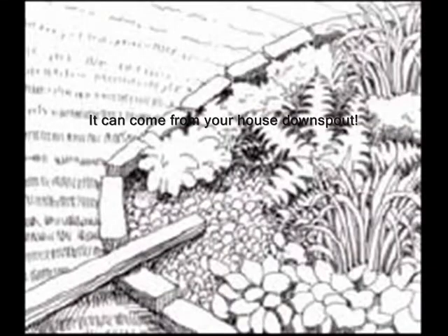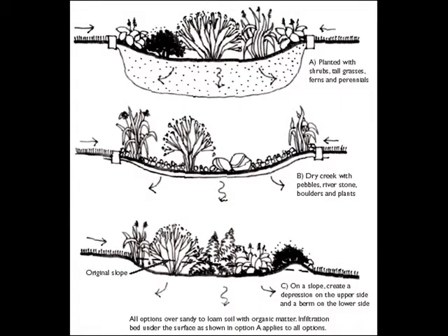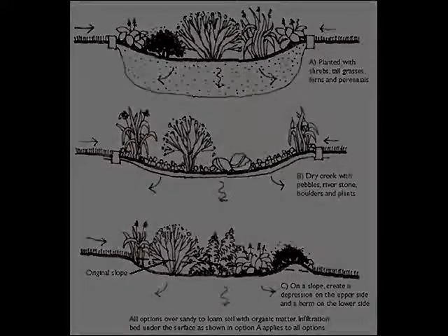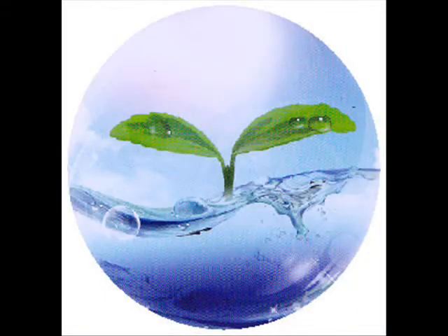Rain gardens are landscaping design features that collect stormwater from impervious surfaces and reduce stormwater that enters surface waters. Instead of routing water from impervious areas into stormwater sewers, the water is first routed to a pervious, low area that collects water and allows it to infiltrate. A demonstration site would not only reduce the amount of stormwater and pollutants that flow into the surface water, but would help educate the public of a relatively cheap installation they could implement near their house or place of business.